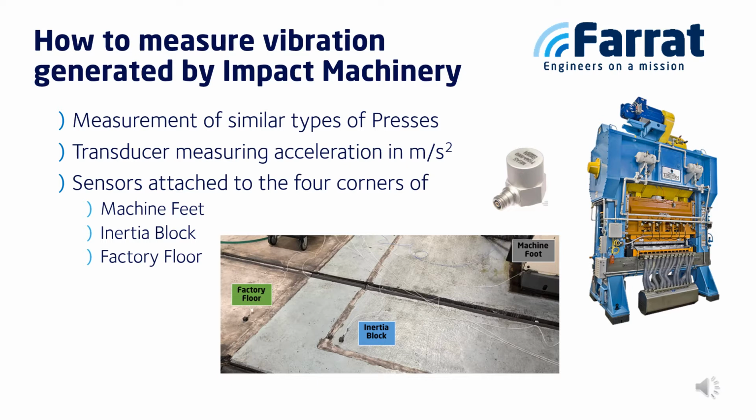In order to record vibration generated by the operating machines, accelerometers were used. An accelerometer is a transducer that measures the vibration or acceleration of motion of a structure. The force caused by vibration or a change in motion causes the mass to squeeze the piezoelectric material, which produces an electrical charge that is proportional to the force exerted upon it. The electrical signal is then transferred to a data acquisition card connected to a laptop that records and processes the data.